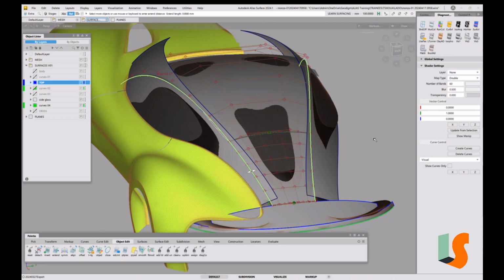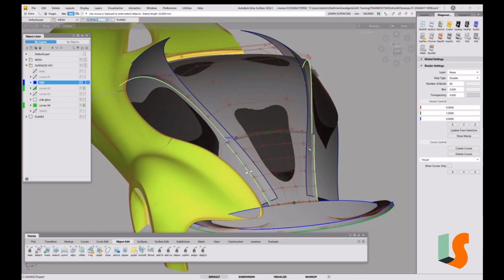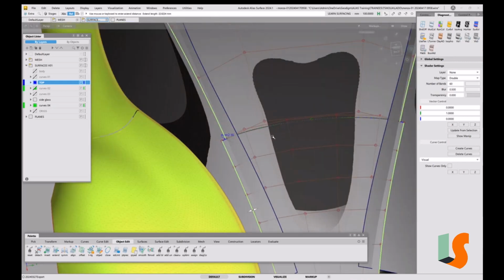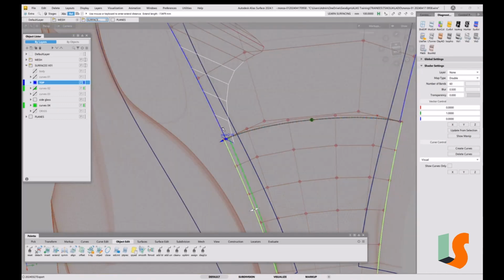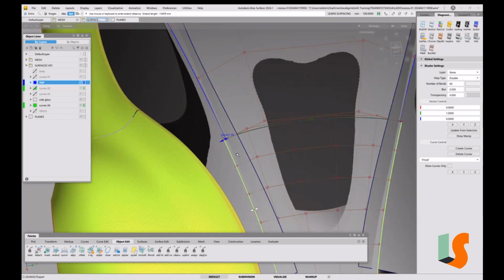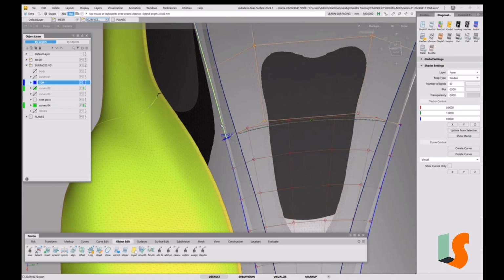I'm just going to extend that through because I need that to intersect. Now, weirdly, extend is working differently on those two surfaces, probably because of the degree, or it's to do with where I picked it or something. So that one I've extended, and you can see it intersects that side surface now. Don't want to extend it too far. And then this one I'll extend out.